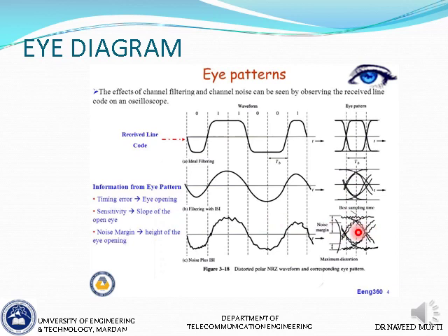So different types of information can be acquired from the eye diagram, and this is basically a tool to visualize the effects of ISI qualitatively. It's hard to measure in terms of volts or units, or maybe you can with accurate measurements, but it is basically designed to give you a qualitative idea of how ISI will affect your system. So having an eye diagram very quickly lets you know about the situation of intersymbol interference.